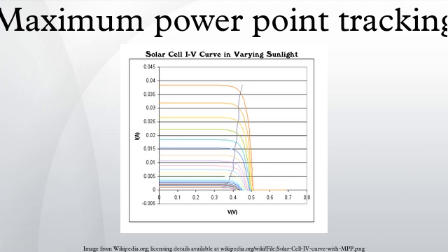In the constant voltage MPPT method, the power delivered to the load is momentarily interrupted and the open circuit voltage with zero current is measured. The controller then resumes operation with the voltage controlled at a fixed ratio, such as 0.76, of the open circuit voltage VOC. This is usually a value which has been determined to be the maximum power point either empirically or based on modeling, for expected operating conditions. The operating point of the PV array is thus kept near the MPP by regulating the array voltage and matching it to the fixed reference voltage VOF equals kVOC. The value of VOF may also be chosen to give optimal performance relative to other factors as well as the MPP, but the central idea in this technique is that VOF is determined as a ratio to VOC.